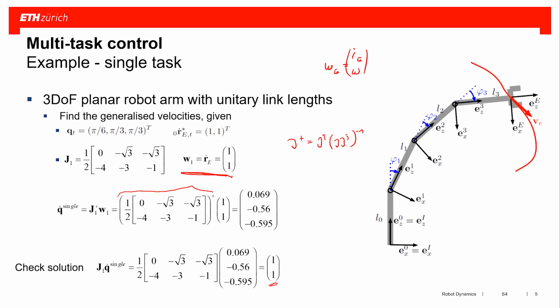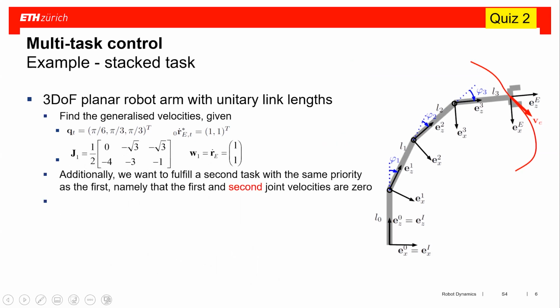This is what this student version is doing with the solution. As I said, we have 3 degrees of freedom in our arm, but we only control 2 degrees of freedom at the end effector. That means we essentially have one direction which remains free. In other words, we can optimize additional objectives in the whole inverse kinematics or inverse differential kinematics problem.